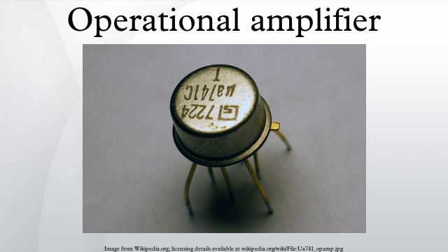Typical low-cost, general-purpose op-amps exhibit a GBWP of a few megahertz. Specialty and high-speed op-amps exist that can achieve a GBWP of hundreds of megahertz. For very high-frequency circuits, a current feedback operational amplifier is often used. Input capacitance is most important for high-frequency operation because it further reduces the open-loop bandwidth of the amplifier. Common mode gain: see DC imperfections, above.